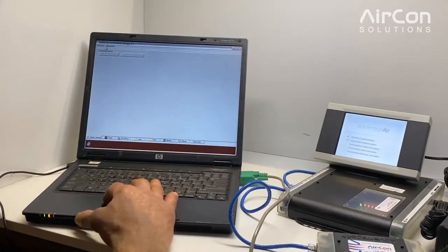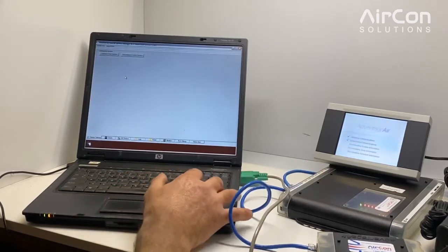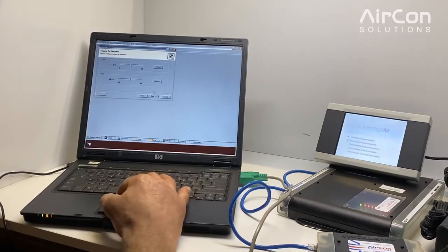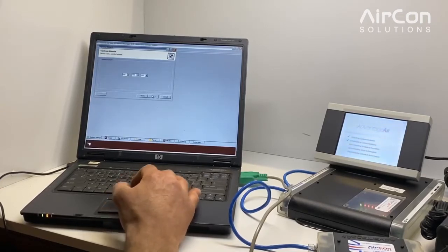I'm just going to give you a quick run through of how we set up a new controller, a new control board. So we're going to configure a new system. Here we can set some parameters for what we want the second stage supply temperatures to be before it starts. We have continuous or intermittent fan operation in heating and cool mode.